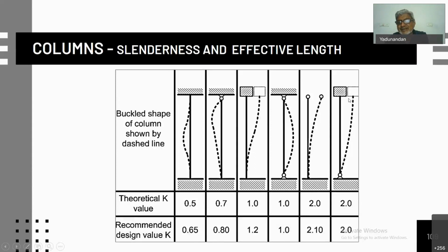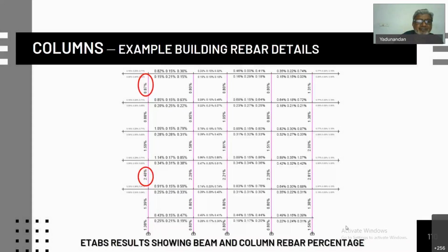Whether it's a completely cantilever-like thing where it is free to move, and the top is not rigidly connected to the column, it will be the maximum. You see these boundary conditions and take the effective length of the column. And you see in the design of the column, you get a maximum moment and minimum moment only at the first story junction, and minimum load and maximum moment condition at the top. You consider these two conditions and provide the reinforcement for the column.